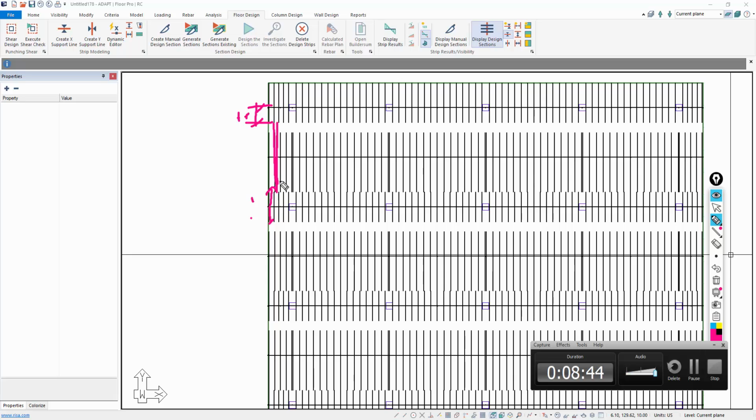And the reason it fills in the balance is because it is labeled as middle strip. So if it was not labeled as middle strip, the program would just lock it at its 15-foot length versus 18 feet, which is the 30 feet minus 4.5 feet on both sides. That's the 21 feet. And so we have this leftover strip width of 18, 19 feet. I think it's, in this case, it would be, actually, I'm sorry, it's 21 feet because this is a 30-foot bay. So this is how the program assigns these tributaries.